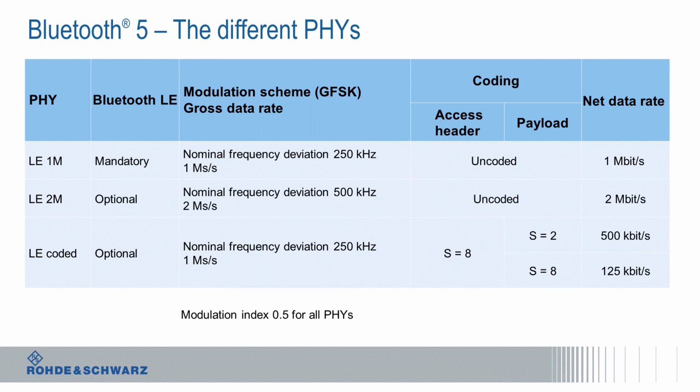We also have an optional stable modulation index, which has been added in for Bluetooth 5, which increases the tolerance to plus or minus 1% from what it used to be, which was plus or minus 10%. This, in theory, can give you a 3 dB improvement in the link budget. There is also the option for the 255 byte payload for advertiser packets, which is an extension.